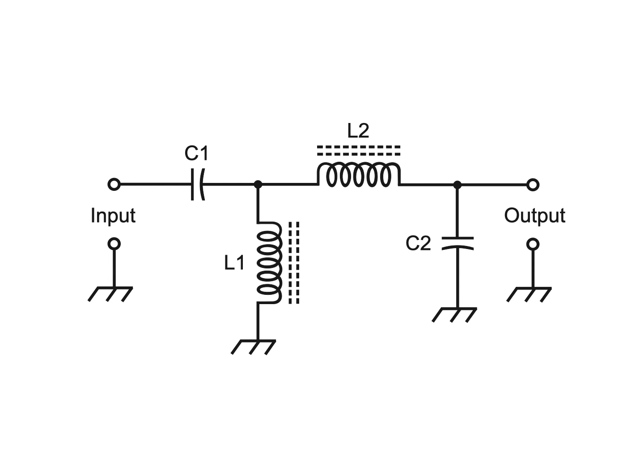If you know how one circuit in a repetitive system operates, then you know, by extension, how all of the circuits work. A problem that occurs in one circuit might also occur in any of the others, and you can use the schematic diagram to track down the problem. For example, if, through testing, you know that an oscillator has changed frequency because of a defective resistor in the base circuit, then if another oscillator of the same configuration develops the same malfunction, you can consult the schematic, locate the base resistor, and conduct some tests to see if it too has gone bad. Without the schematic, you'd have a hard time locating the proper resistor.